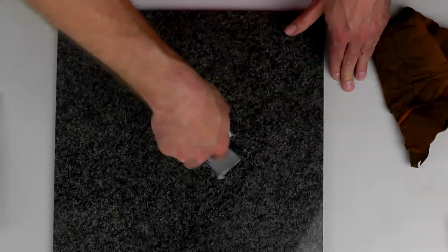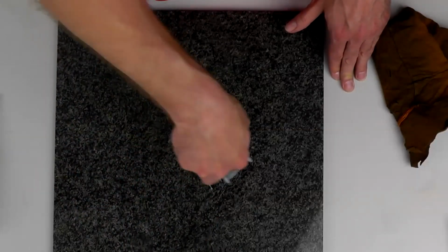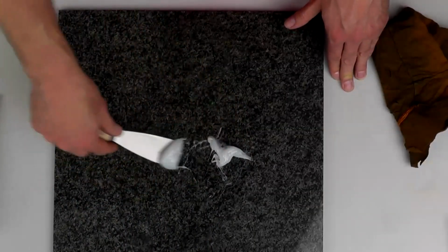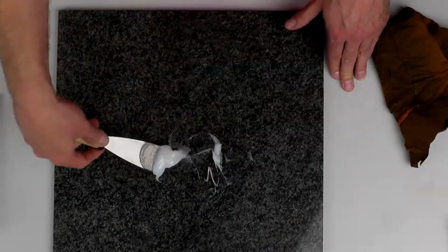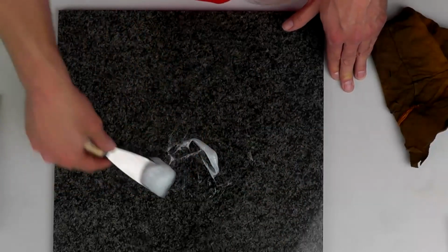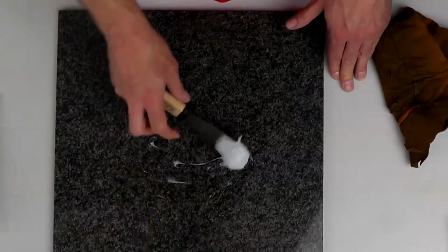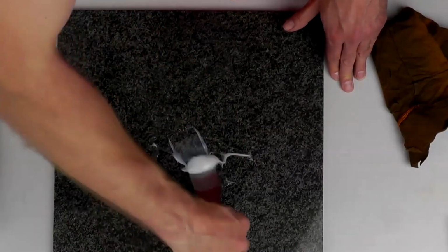And here it comes to the proper mixing because this is an epoxy, so it's an adduct system. It's a key lock system. So two parts of the A component have to get in contact with one part of the B component. If this is not happening, then you will not have a proper cure. So please spend at least 30 seconds, 1 minute to get a good mixing.